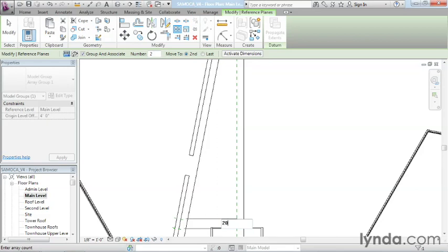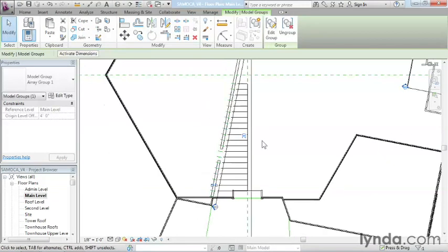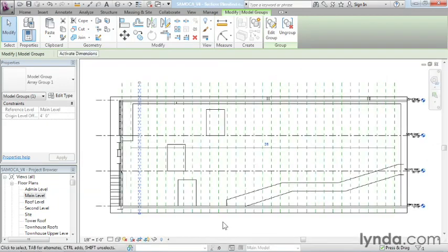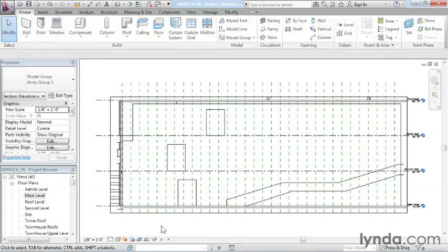So if I put in 20 here, you're going to see, if I zoom out, that I now have 20 of those reference planes. If I click it again and I say, well, what about 30? And it actually turns out that for this design, I need 31. So that's the number that I'm going to settle on. What that does for me is, when I open up the section again, it gives me all these guidelines right over here. And now you can snap your voids to those guidelines, and even though the voids are varying sizes, they'll all be lined up on the same verticals.